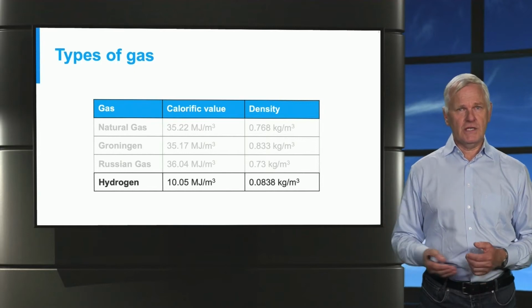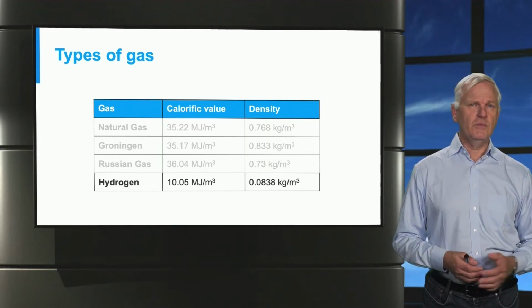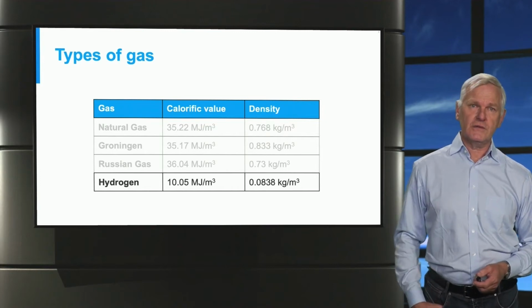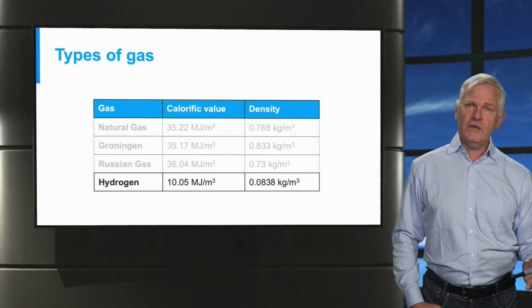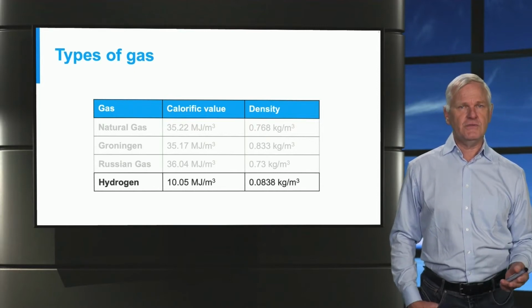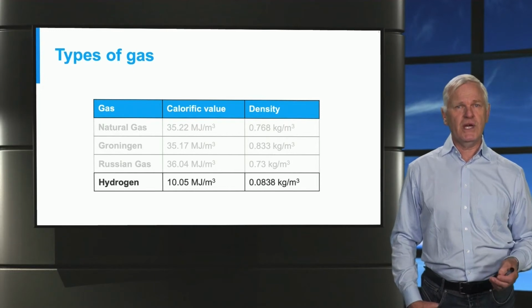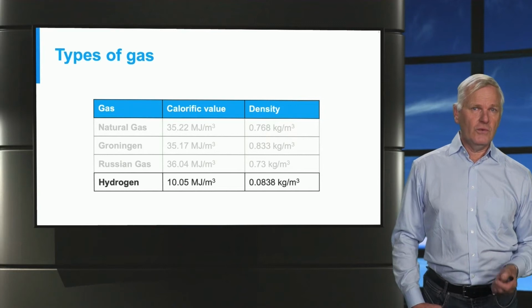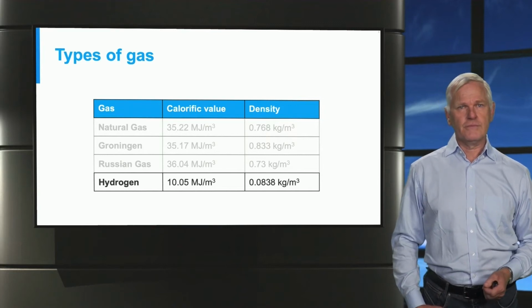To use these gases in a house, a city or an industry, we must remember that most burners or furnaces are based on specific calorific values. If the calorific value of the supplied gas differs, we have to mix it, for instance, with nitrogen to get it back to the original value. The mixing should be accounted for in the simulation as well.